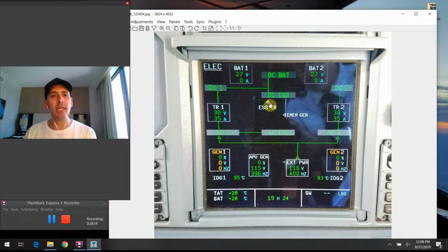But also from a heat standpoint, with DC currents, passing this much power through the system creates a lot of heat. That's of course a fire hazard for us, and we want to mitigate that as much as possible on airplanes. So with an AC power system, you don't have as much heat generation as we pass the power through the system. So just a couple things to make mention of that you might be wondering about.